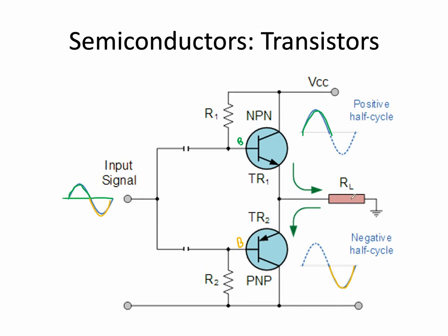So if you hook this up, they just throw a little resistor here, but connect this to a speaker instead. You can take a small input from a guitar pickup or a microphone and drive an actual speaker. Yeah, there's a few more parts involved. It turns out you've got to have some bias resistors and capacitors in there. We haven't talked about capacitors yet, or resistors exactly. But yeah, you can make a very simple amplifier.